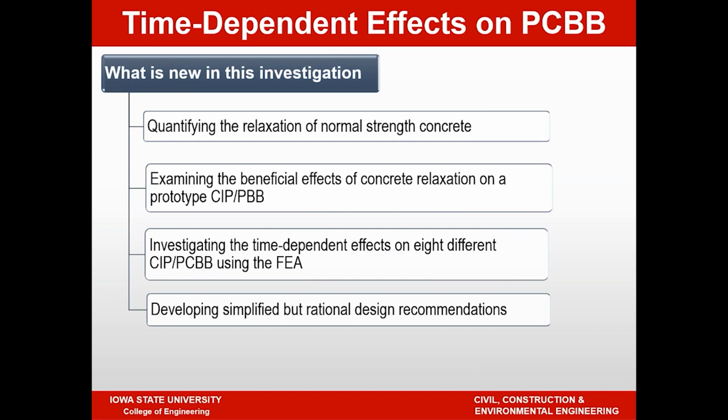So in our study, we wanted to capture the relaxation of concrete directly. The typical approach in the past has been to take a creep function and reverse it to establish a relaxation function. Creep and relaxation are treated as interchangeable, which is not a bad assumption. Past research has shown they can be used interchangeably with appropriate reversal of the function. However, there has also been research published suggesting that the two phenomena are not necessarily identical,